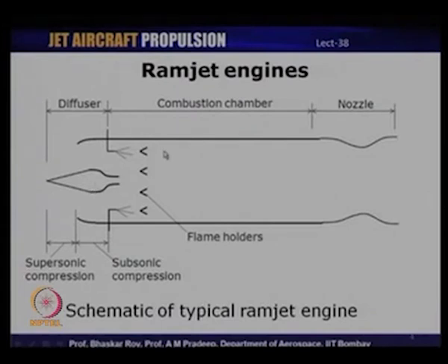It is very similar to a ramjet, but combustion in a scramjet occurs at supersonic speeds, which means that you do not have a subsonic compression there. Flow is only decelerated through oblique shocks, but it is still supersonic, and scramjets are designed to operate at very high Mach numbers, above Mach 5, that is in hypersonic speeds.